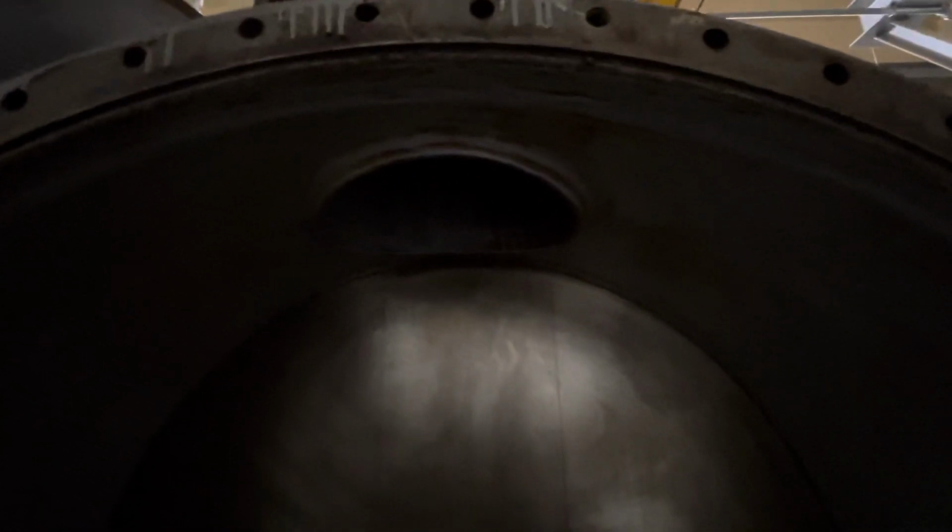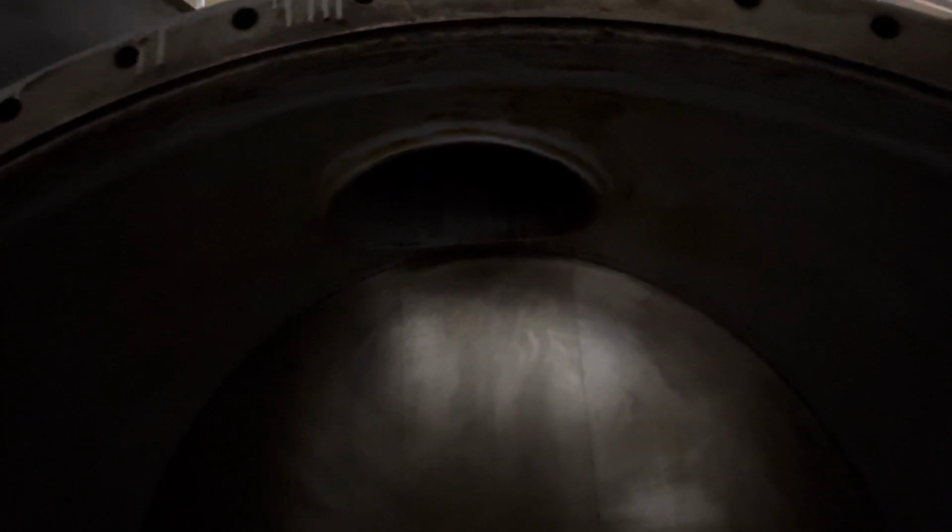This flow sensor is working as a safety. If there is no flow, it will trip the chiller. And the temperature, the inlet and outlet temperature, it will show you. In the same way as the condenser, in this evaporator, inside the tube there is chilled water. Outside the tube, there is freon.